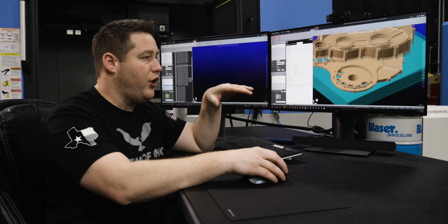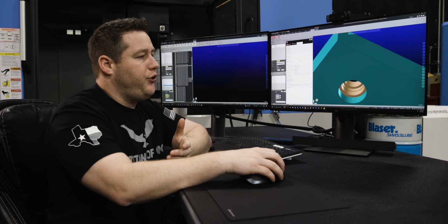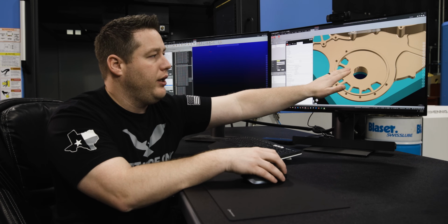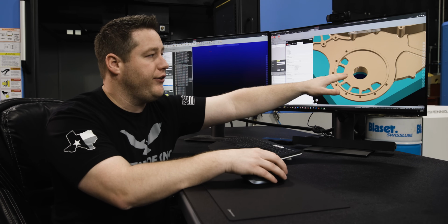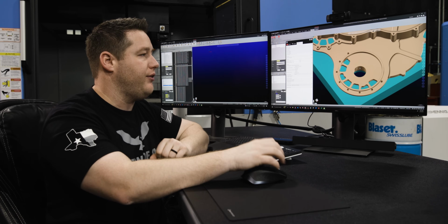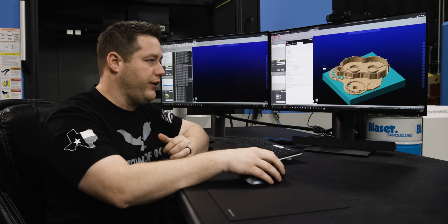Now, if I did have undercuts that I do want to cut, and I don't want it to try to do that here, what I would do then is create my collision avoidance model with this same size hole right here. I want it to cut this hole, but I would create it as the same size as that hole. And then it would see that there's not an undercut there.